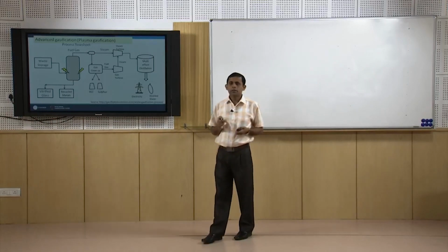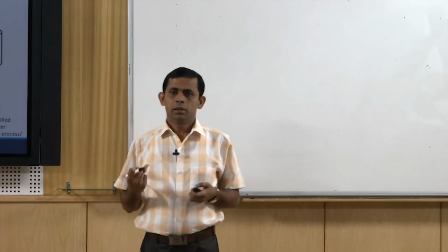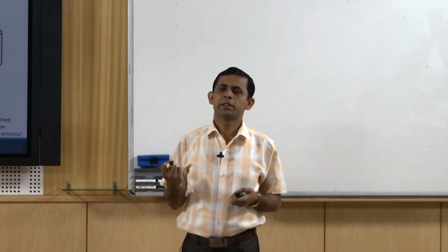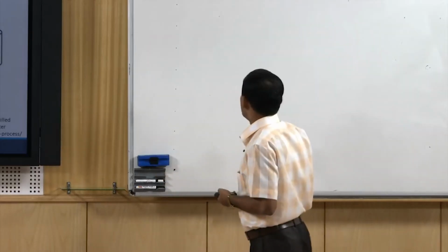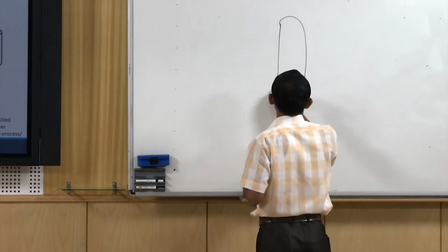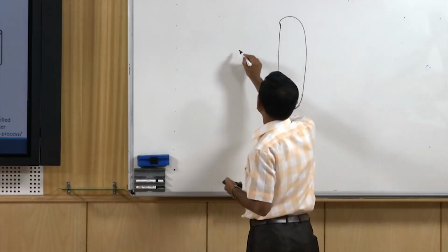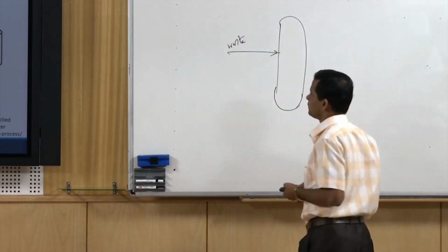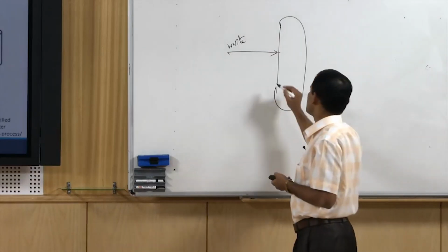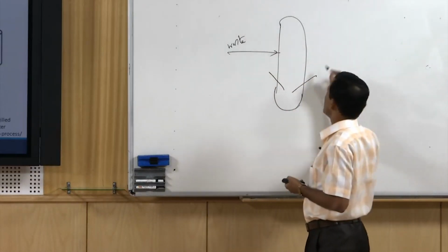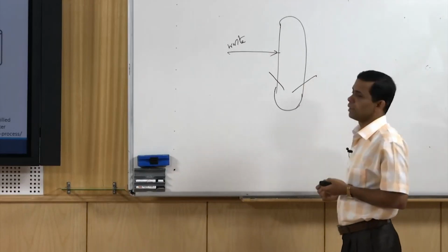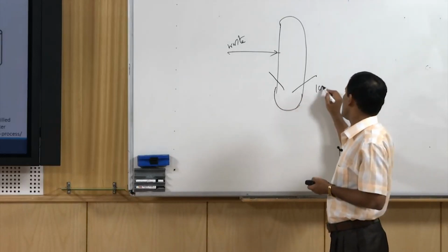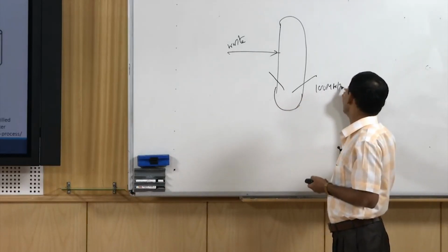So the main change will be with the pretreatment. In the case of an entrained flow gasifier, pretreatment is essential, but in the case of a plasma gasifier no pretreatment is required. So the waste can be directly charged to the gasifier without any pretreatment. Another thing is we do not need to supply oxygen or air; instead we will give an external source of very high voltage, which can generate 100 megawatt per meter cube power density.